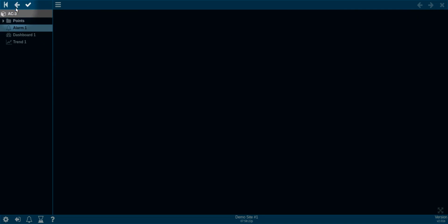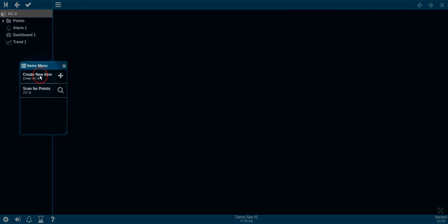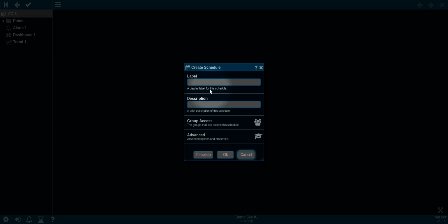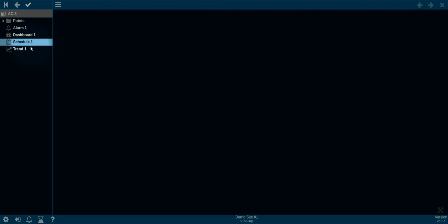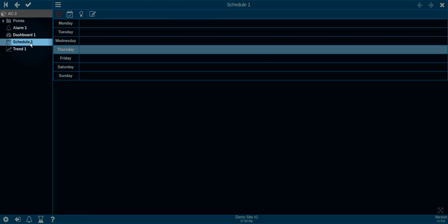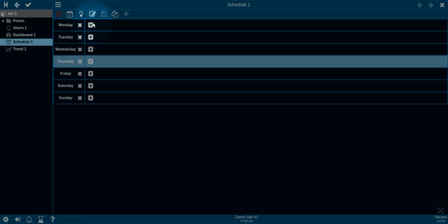So let's go ahead and close that. And we will create a new schedule. Put schedule 1. And then view the schedule. Put it in edit mode.